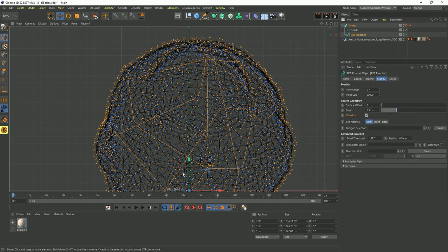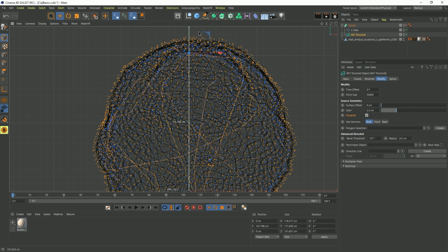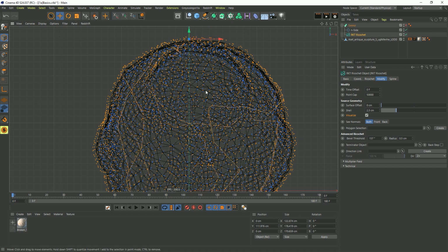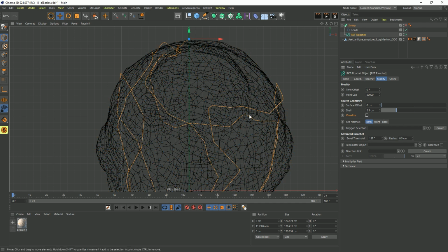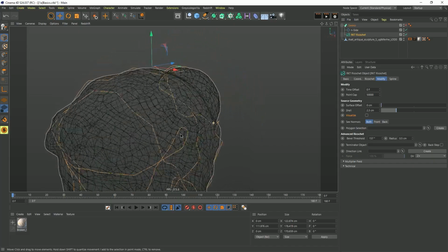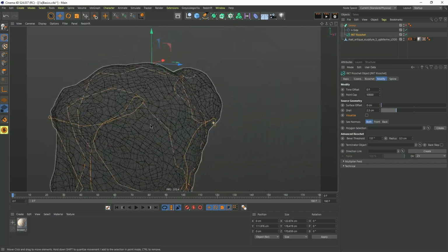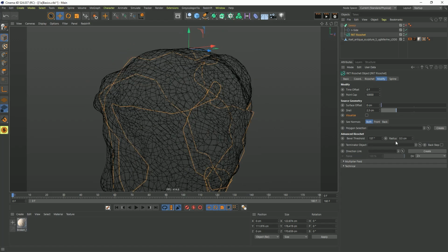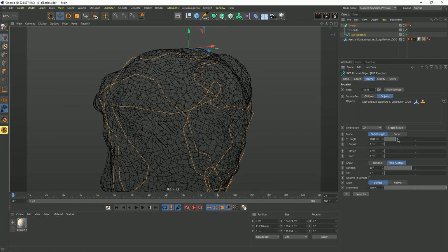All we need to do is move the Ricochet until it starts in between those two layers. A good way to do this is move it out and then move it in until suddenly we see it reacting, and now it's in between those two layers. From the front view, it's really hard to tell. Let's turn off the visualize, and now let's go to the 3D view, and now we can see as I rotate around that it's very well trapped in between those two layers.